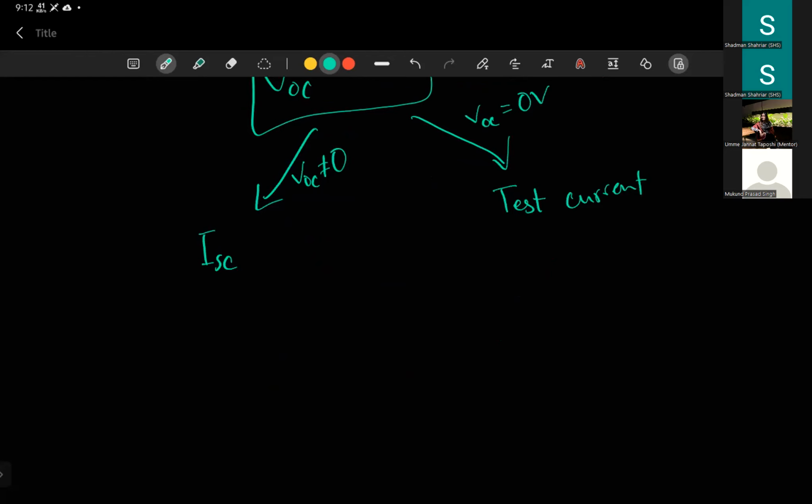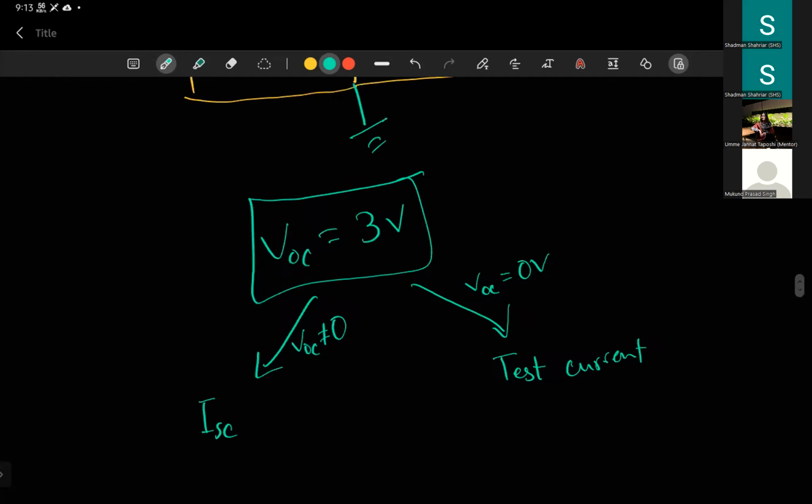If you have an inductor and you're trying to do, say, Norton's theorem, or finding the current first, you can find the VThevenin by doing VOC and RThevenin by doing VOC by ISC, if you have a non-zero ISC. This also holds for ISC.